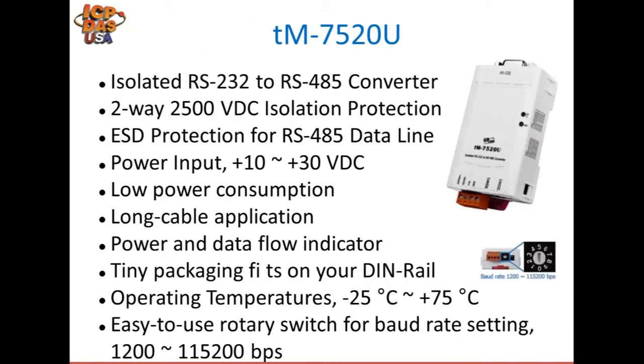The TM7520U is a smaller form factor than the I-7520. Another important distinction is that the baud rate can be set by a dip switch or it can be used with the auto baud/self-tuner. The benefit of selecting the baud rate instead of using the self-tuner is when working with longer distances or noisy environments.